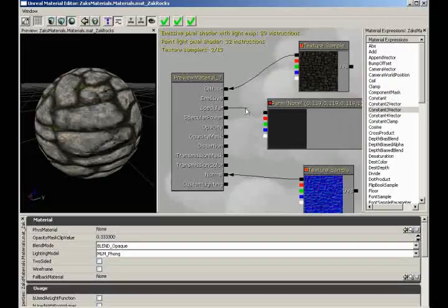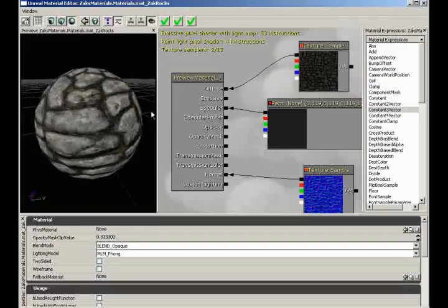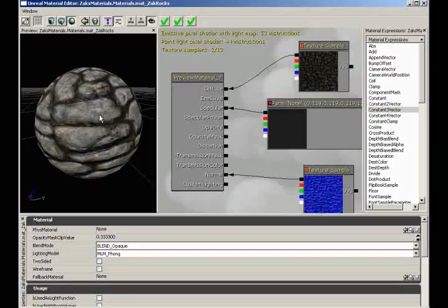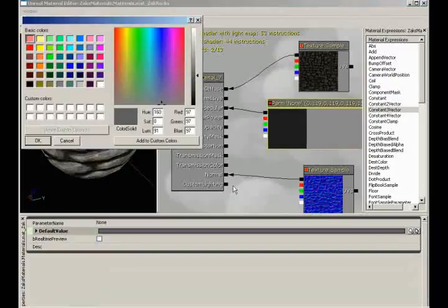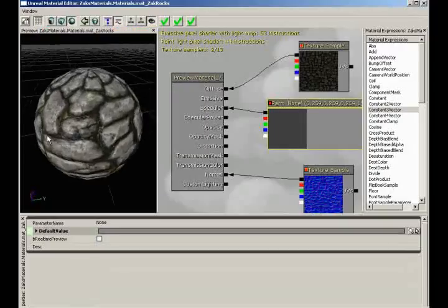you'll notice that there is a change that takes place. It's subtle, but it's there. And I want you to keep in mind, if you're completely new to this, the power of subtlety. Sometimes the greatest difference that will push your material from something that looks good into something that looks realistic, in a lot of cases, it's just going to be a subtle tweak. So don't ever think that, well, I need my rocks to be shiny, so let's go ahead and go for a super white hotspot. In a lot of cases, you don't need that. In fact, a rock, if it has any shininess at all, because you don't necessarily want it to look like chalk, it's just going to have a little bit.